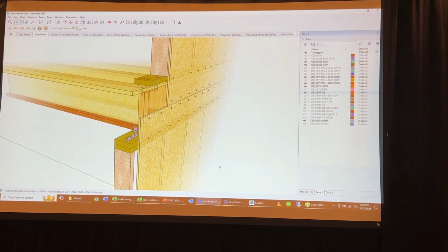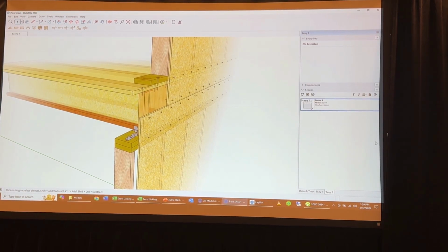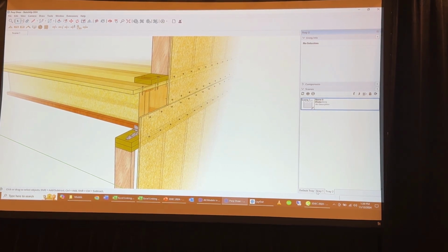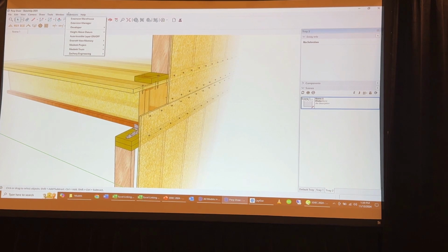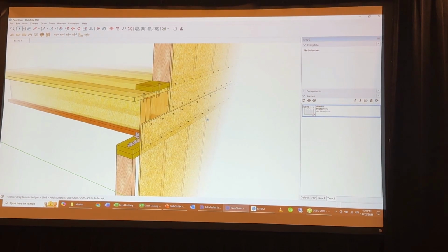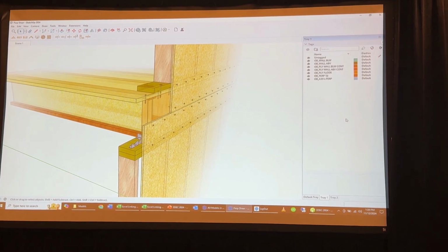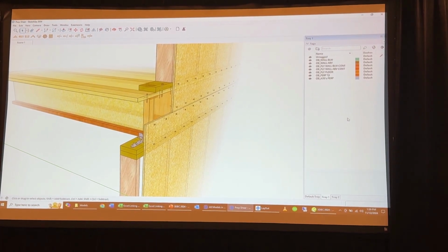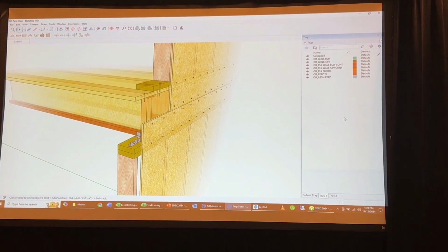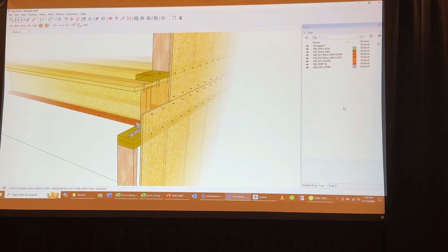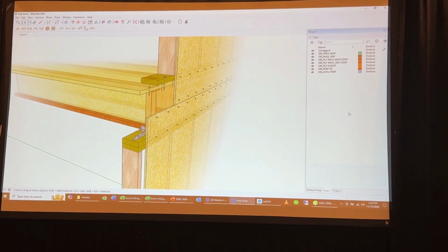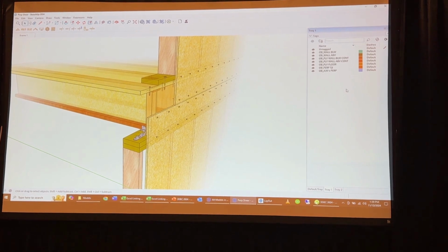So how do we do that? How do we create that? It was actually much more difficult before we discovered the auto visible layer. For those that do not know how that works, we can turn this on. Now every layer that we add past this is not going to go to any existing scenes. We've done that before, everyone. I'm assuming in SketchUp you make a layer and then every single one of your scenes you have to go back and redo. Total pain. Takes a bunch of time.